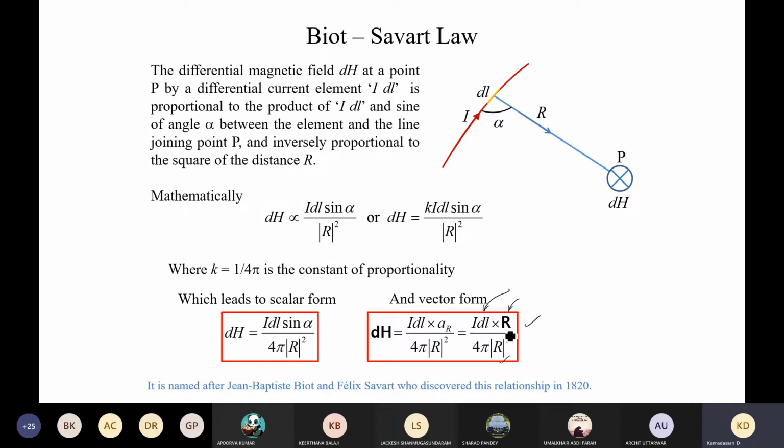So this also indicates how the magnetic field is flowing. Whenever a current is flowing, we can apply the simple right hand rule, which says that the magnetic field will be just around that in the anti-clockwise direction. Whenever the current is flowing in the opposite direction, then the field will be exactly opposite. Because of that, whenever there is a structure which is not infinite, most probably people tend to use the cylindrical coordinate system to describe the behavior of the magnetic field, which is just around that.